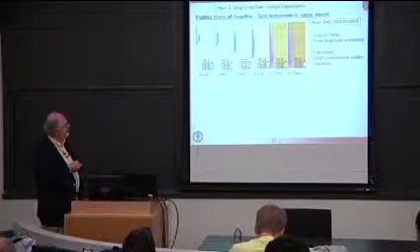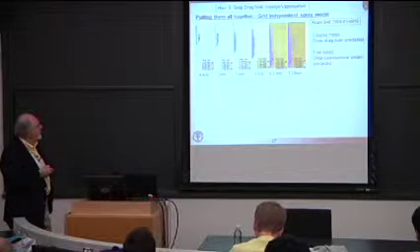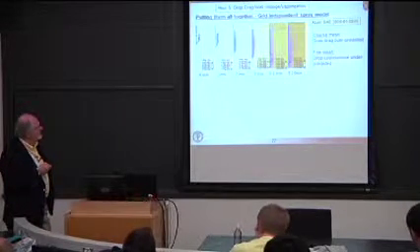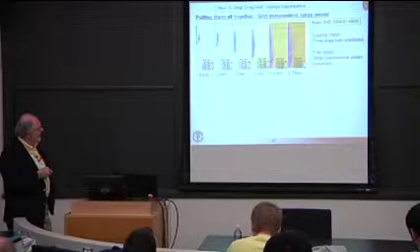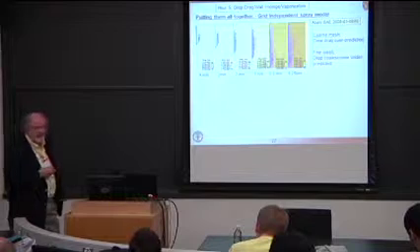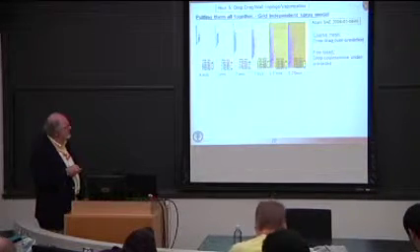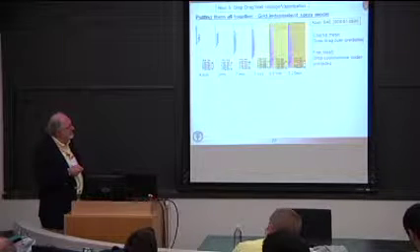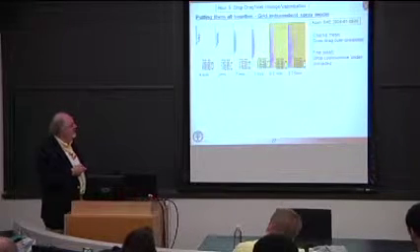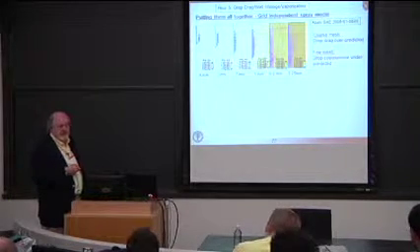I had a 4 millimeter mesh, so each of these mesh cells is pretty wide, actually. And the spray at a given time after the beginning of injection reaches a certain distance. If I now refine the mesh size, I see that my spray penetrates further. And finally, I have to get to very fine meshes before I see the spray actually penetrating to a fixed distance. And the reason for this is essentially that on a coarse mesh, the drop drag effects are